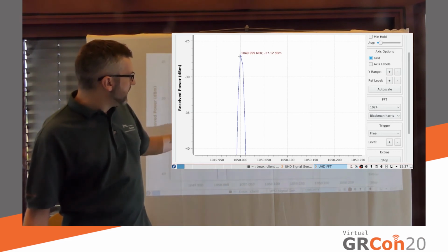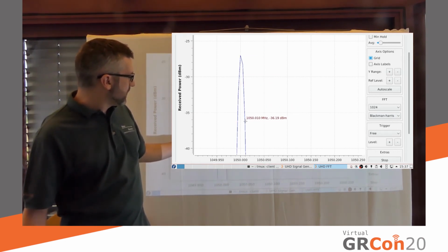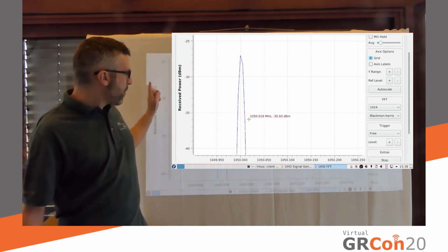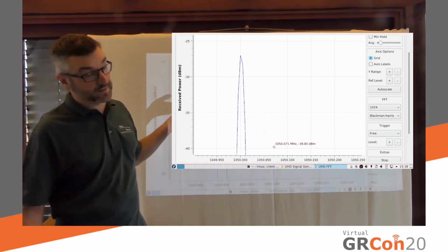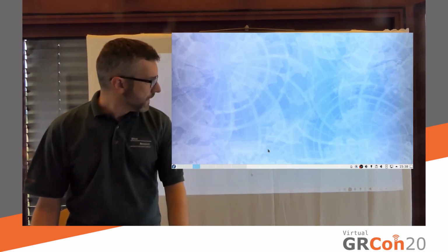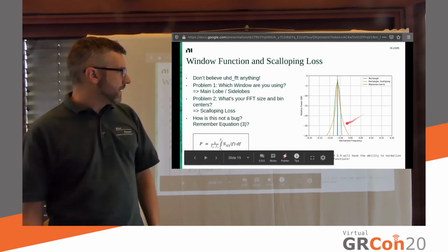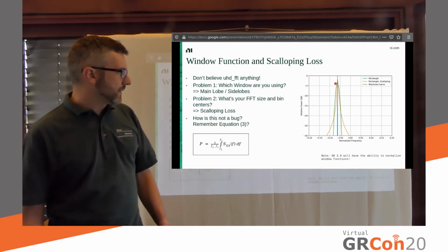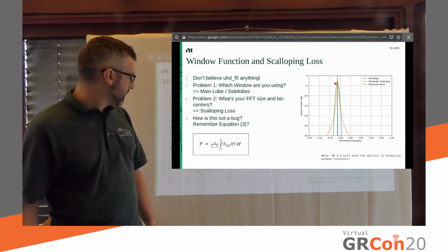That's because the energy coming from the sine wave is actually distributed within these FFT bins. So this should really read dBm per FFT bin after FFT processing. It's a bit too unwieldy, which is why we leave it as it is. Here you can see what happens with different windows, and also in a rectangular window what happens when you don't exactly hit the FFT bin.